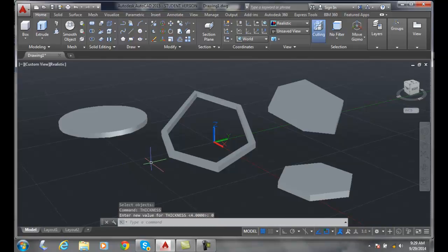So this is not the fix-all-ends, but you want to make sure that these are closed generally. It's got to have a thickness, which is an old-fashioned way of doing 3D, of just saying we're going to give everything a certain thickness in the Z direction, and we can convert those to a solid. I'm not a big fan of these because you generally could have made these in much better ways, probably. For example, this could have been a cylinder, right?